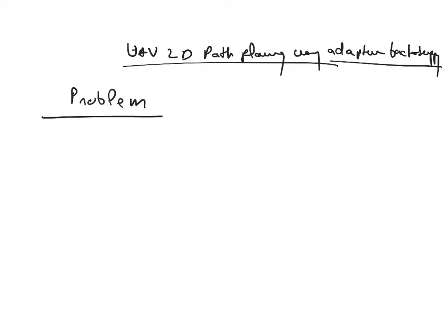So we are given, let's consider a fixed wing UAV flying at a constant altitude. Okay, so the height doesn't change, and you can change height over the spring break. And so the problem is like this. So the position vector, z dot, is given by v of s psi. Like it's a shorthand notation, right? So v is the velocity, which is nothing but v cos psi and v sin psi, right?